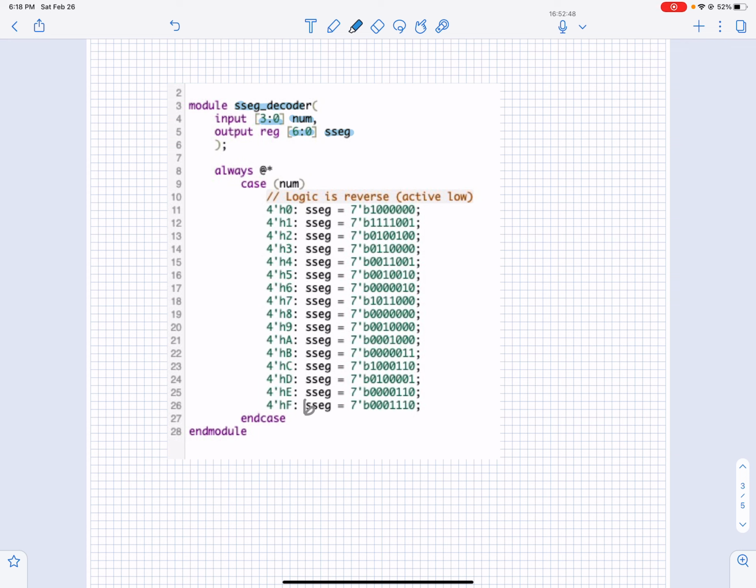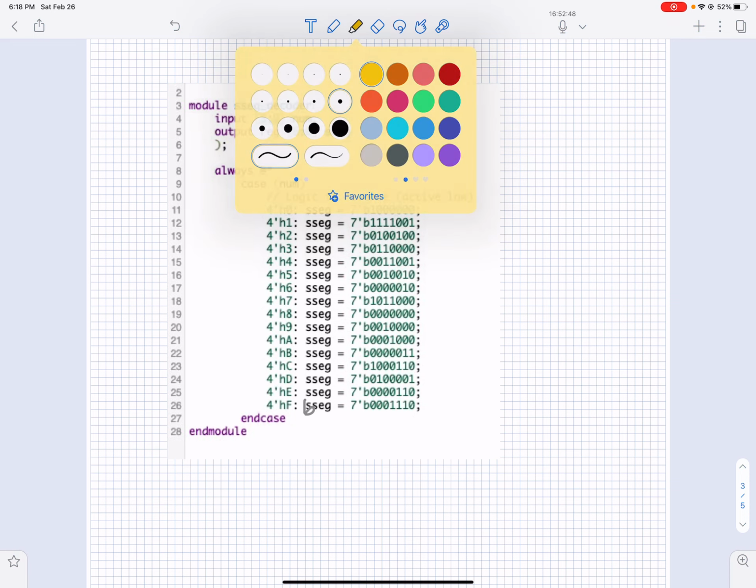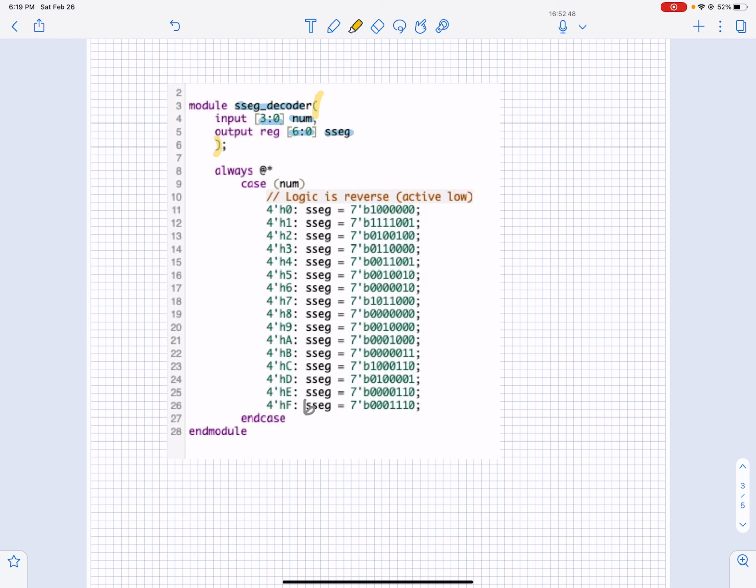This is a new thing, but it's got similar features where we still have a description of a module. We put in parentheses, let me highlight that, parentheses defining our inputs and outputs, and then we start with an always statement, okay? Now, one thing that's different with an always block, and we haven't used always blocks before, is there's a sensitivity list that's associated with an always block. And so you'll find that sometimes within an always block, you don't need to be sensitive to every variable, especially when we start doing sequential designs. But let's defer that for now.